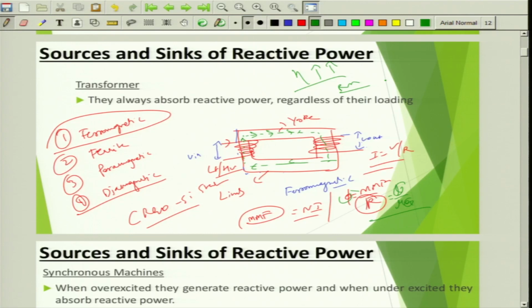Now anyway, this transformer is present, and how is the EMF produced? Because there is a sinusoidal time varying flux linking upon constant or immovable conductors. Time varying flux touching upon stagnant or stationary conductors produces an EMF which is known as statically induced EMF. And there is Faraday's law of electromagnetic induction, which helps us understand that EMF gets induced, which is minus N d phi by dt, the rate of change of flux. Because input voltage is sinusoidal, current is sinusoidal, flux will also be sinusoidal, it's time varying.